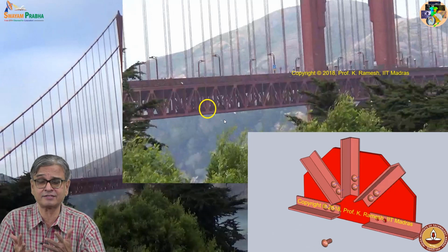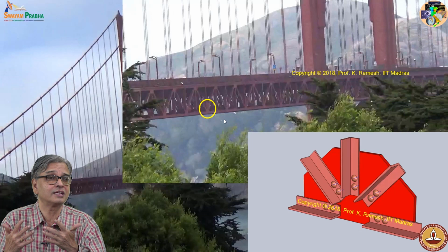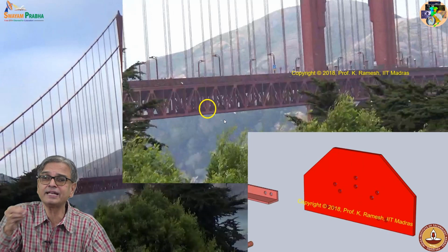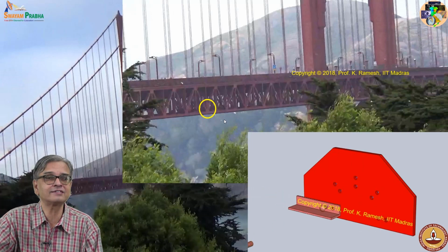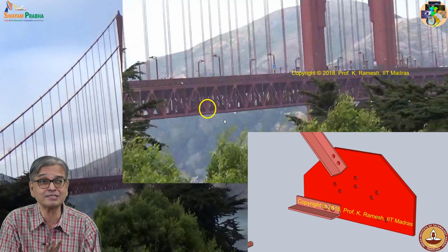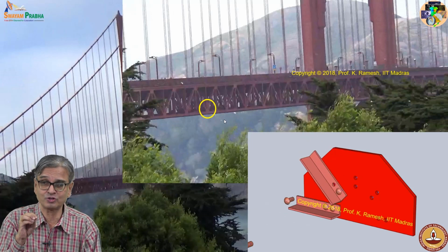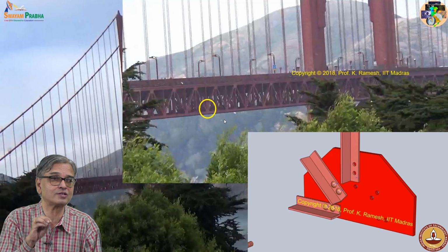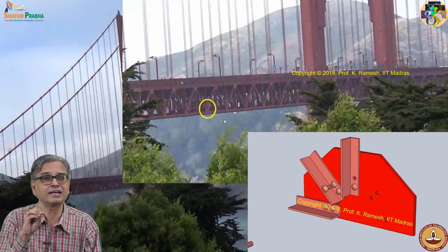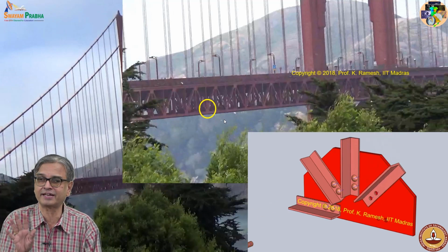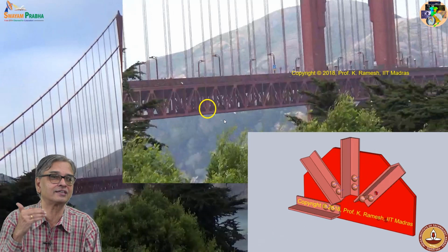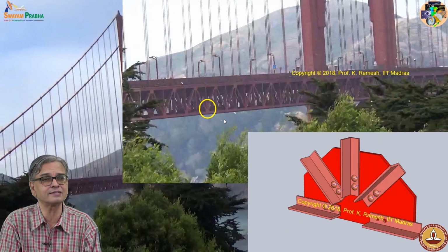Even if it bends, even if you have to consider the self weight, you simply lump it in the joints and then proceed as an approximation. Because now you have software which will find out the actual stresses, and then it's all very efficiently designed. Okay, don't carry the impression that you do a crude analysis in your class. The same thing is practiced in real life.